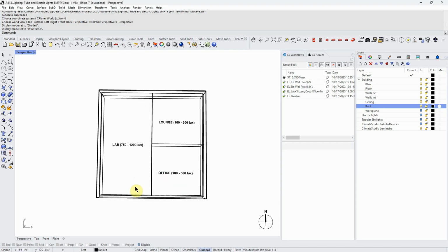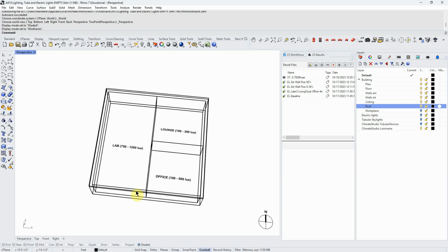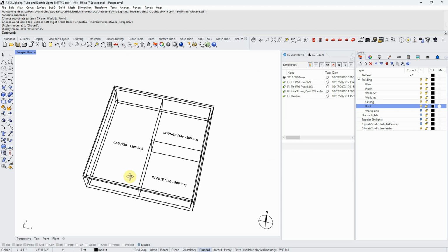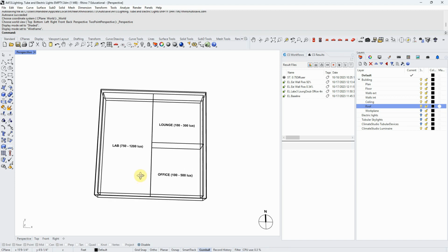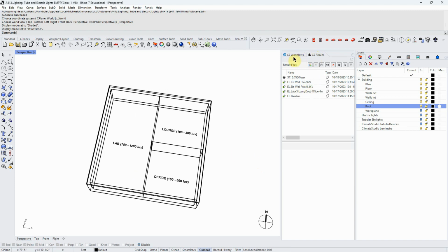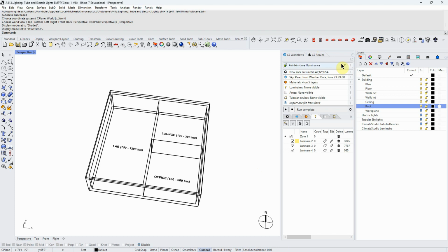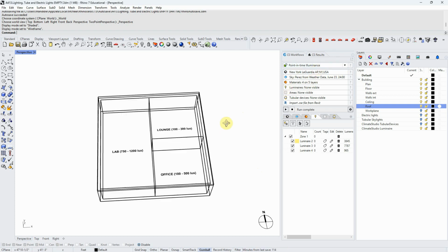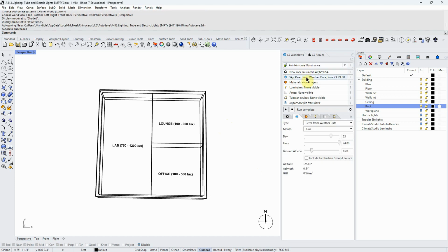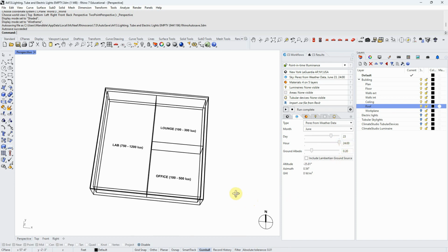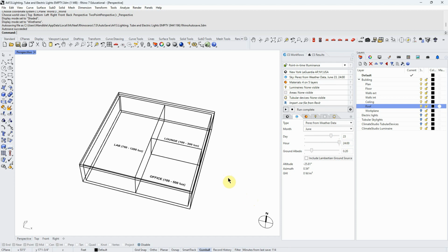And these are the targets that we need to, in this case, try to design electric lighting that will meet. So how do we do that? The first step is which simulation workflow are we going to use for electric lighting. We can use a point-in-time illuminance. Why is that? Because we can essentially turn off the sun. So if we set it for any day to midnight or nighttime when there's no sun, then the only illumination in the building will be from our electric lights.